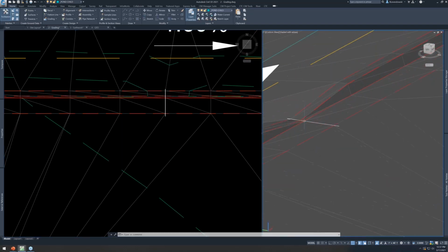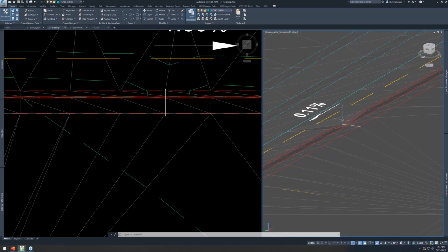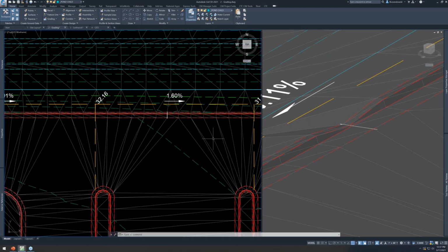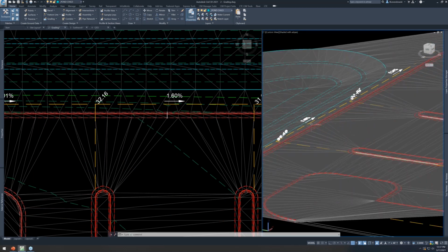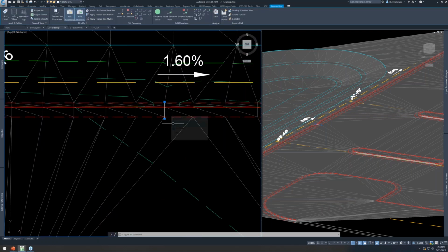It happened pretty quick, but you saw that curb cut come right in there, right? So it pulled down those top and back of curb feature lines to force a curb cut in there, okay? Now, there's two ways to do this. If you continue to work with your parking grid surface, since this feature line is relative to the parking grid surface, it'll move up and down with it, continually forcing that curb cut.